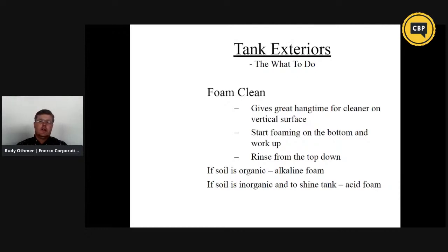To make sure you get good distribution of your cleaner on the surface, you want to foam starting at the bottom of the tank and working your way toward the top. Opposite of that for rinsing it down, and you want to rinse before the foam dries. Rinse from the top toward the bottom. If it's a boil over or a spill, etc., you've got organic deposit on there, you want to use an alkaline foaming product.